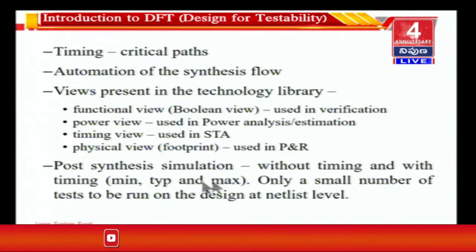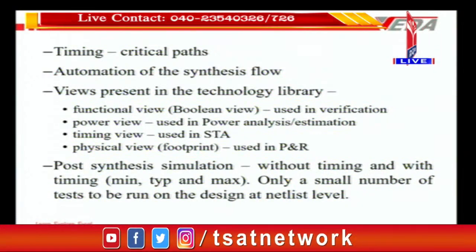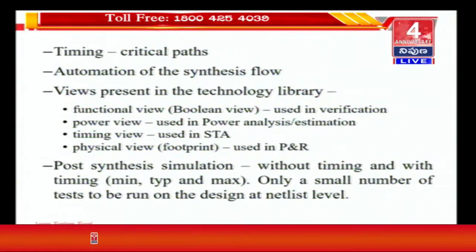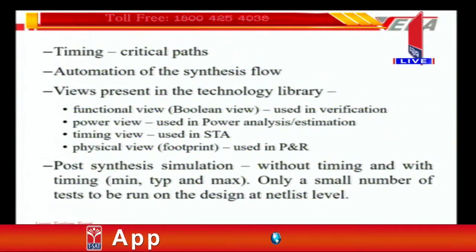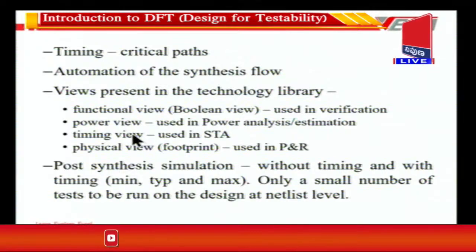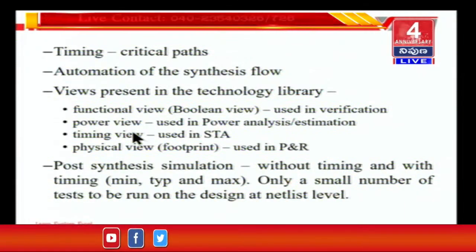Okay. So this simulation, post synthesis simulation, can be run with timing and without timing. Without timing means that if in the command line itself you give an option like no timing, then it will not take the timing information from the cell library, from the technology library. It will not use the timing information; everything it will set to 0.